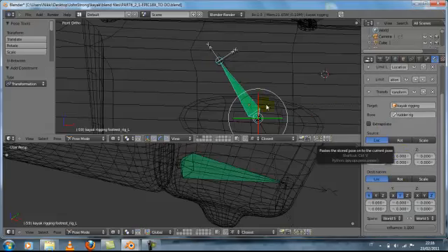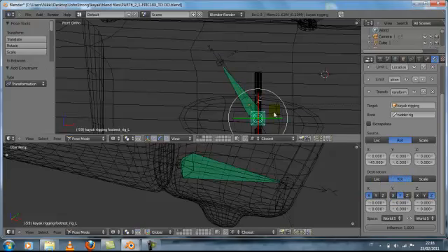So the footrest behaves like the destination, while the source is the rudder. For the rudder, we said that it has to rotate along the x-axis. So set 45 degrees. We are working on the left footrest, while the destination, remember the destination is the footrest, and set always rotate, but this time along the z-axis.